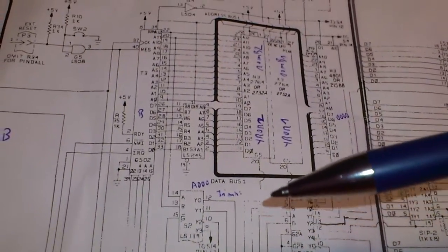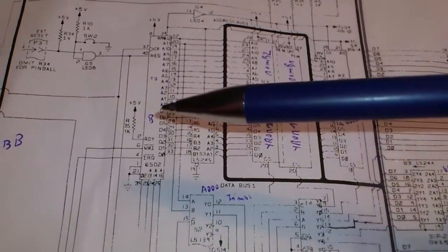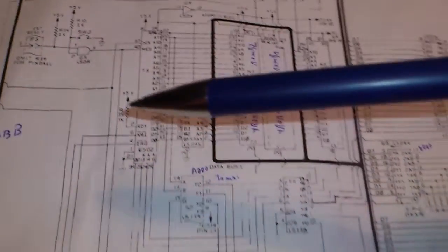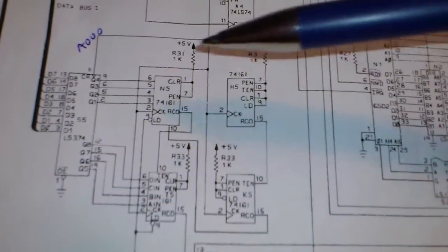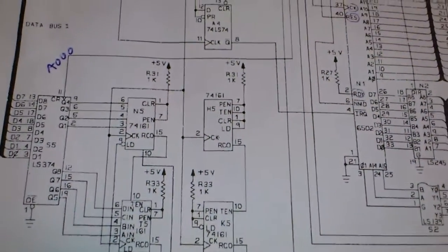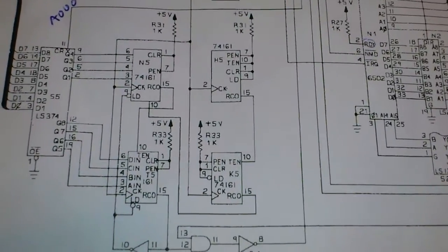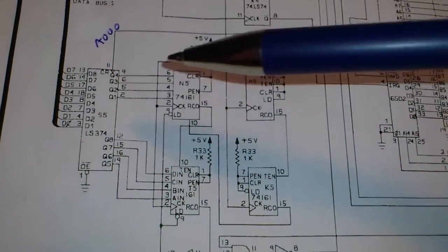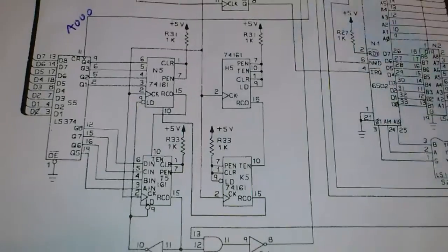Now, one important thing, and that took me quite some time to figure out, is this guy is getting a tick reference or a time base from a timing logic on that side here. On the first generation soundboard, there was this RIOT component, which was the RAM, I/O, and timer. So this one was giving a timeline or time base to the CPU. This has now here on the second gen card been reproduced by some kind of discrete counter logic.